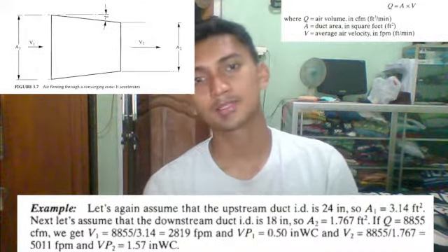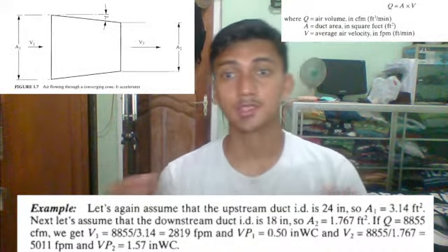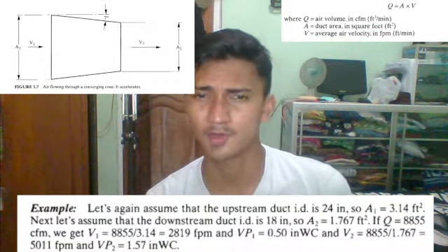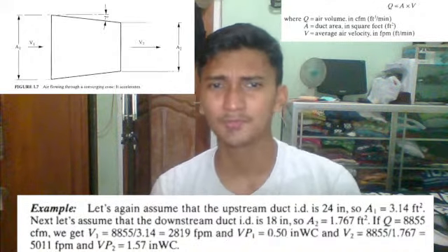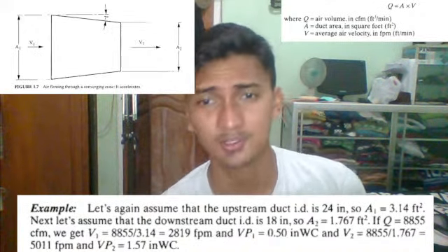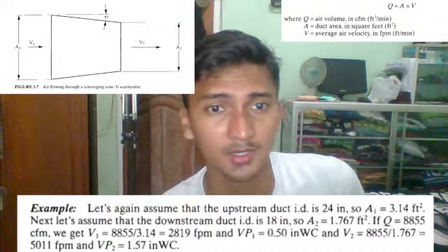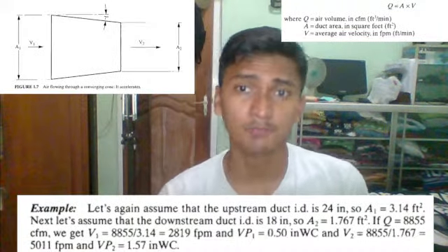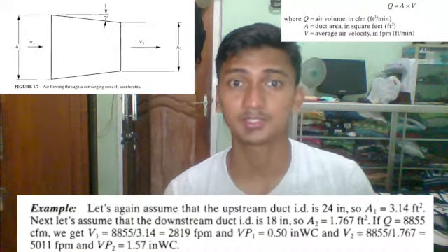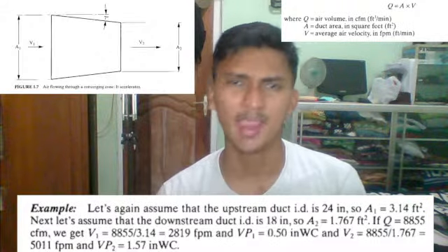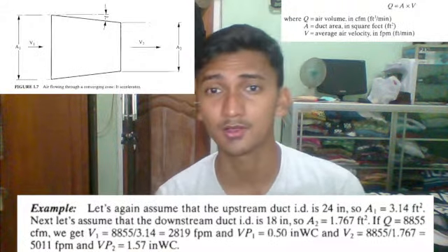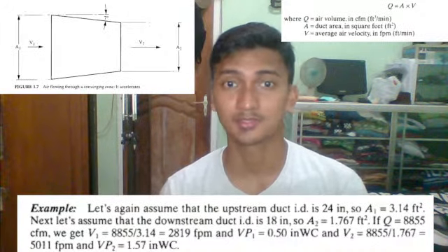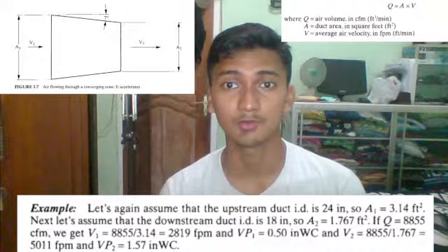A converging cone past a fan is often used to increase the air penetration for applications such as spot blowing or comfort cooling. A converging cone past the scroll housing of a centrifugal fan usually works without any problem, right? Care has to be taken, however, on a converging cone past an axial flow fan, because there often is air spin past an axial flow fan, even if it is a vane axial fan with guide vanes that are supposed to remove the air spin.